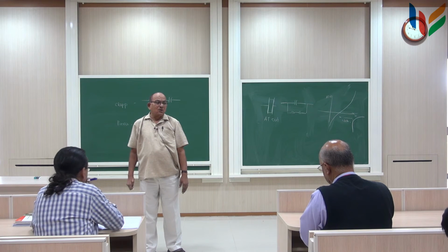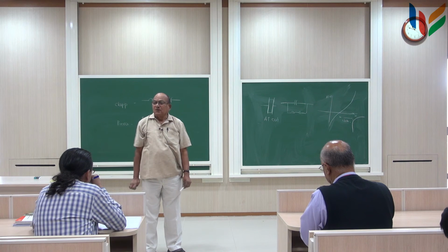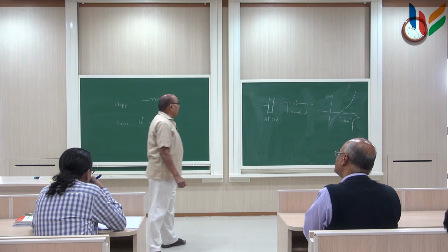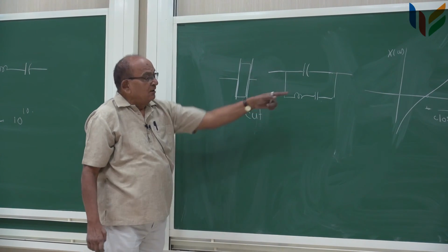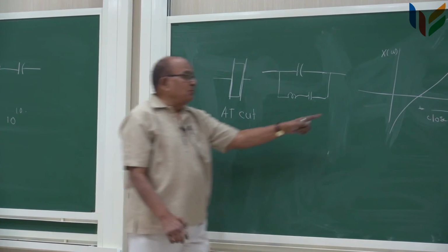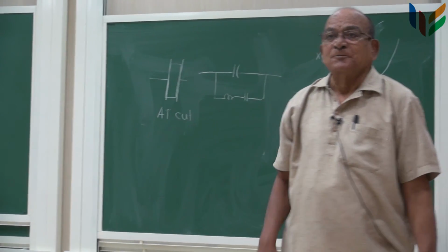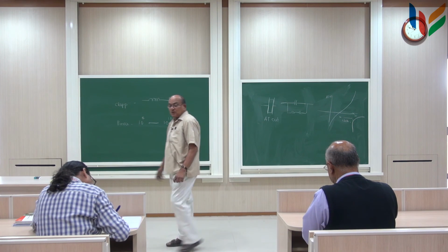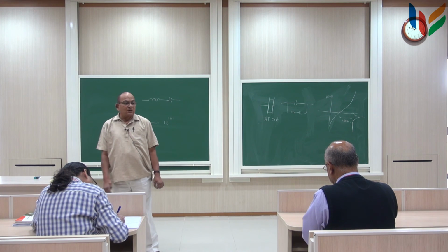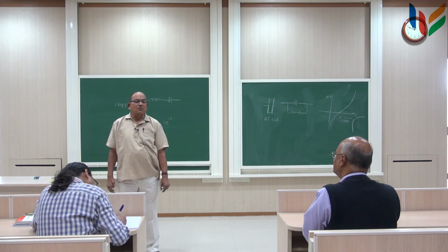So, if you cut that quartz crystal at that particular angle and take a small slice of it, a rectangular piece, and then put it between two electrodes, you will get these two frequencies, which depend upon the size of the quartz piece. So, you can buy a quartz crystal for a resonant frequency from the market and then put that into the circuit and make your oscillator.